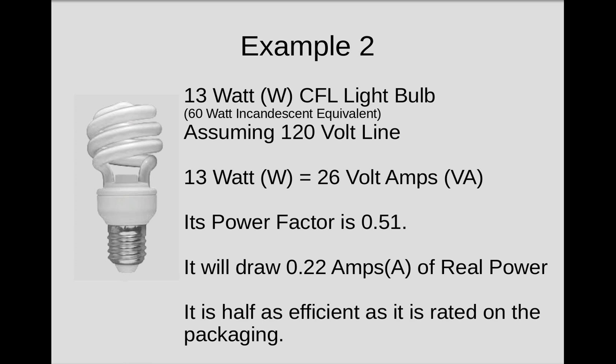If it's a newer light, and a lot of the newer lights have been required to be marked like this, you'll notice that the inside of the light will be marked with a 40 watt bulb or a 7 or 9 watt CFL rated light bulb. The reason they're doing that is because people don't understand what the power draw is actually of the CFLs. Just because they're rated at a lower wattage does not mean they draw less current all the time.